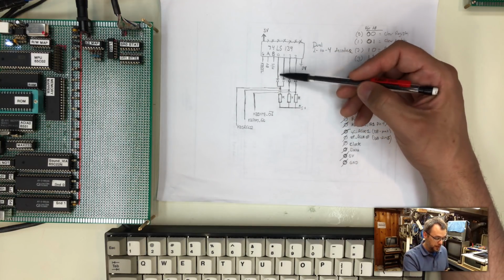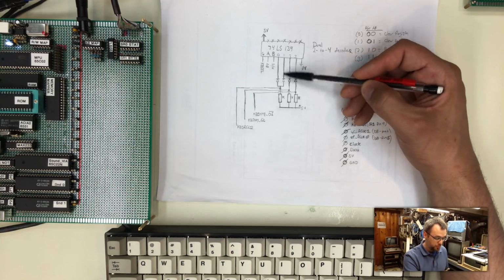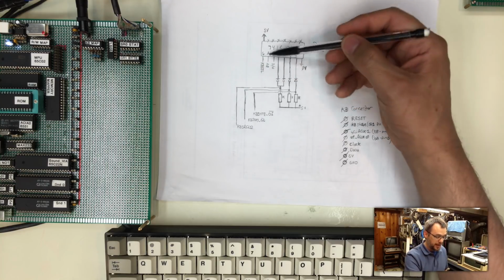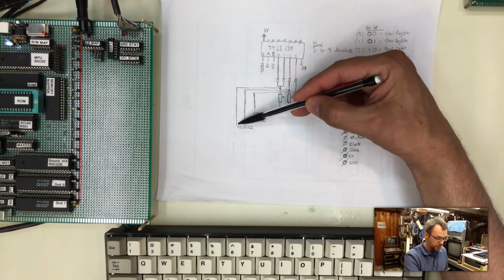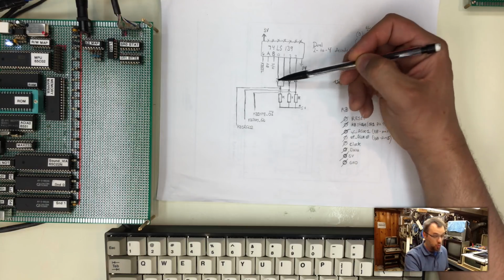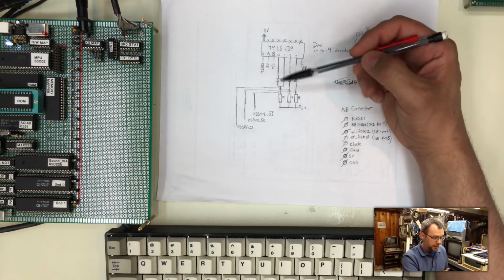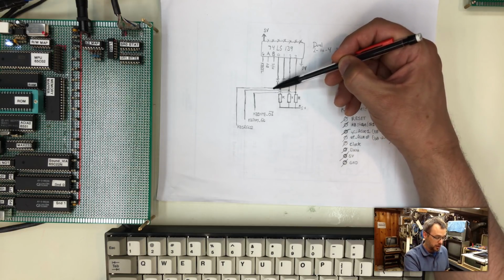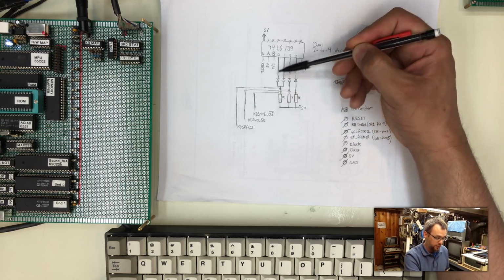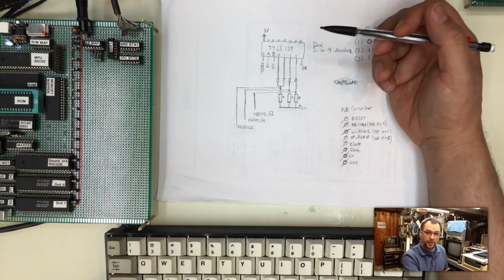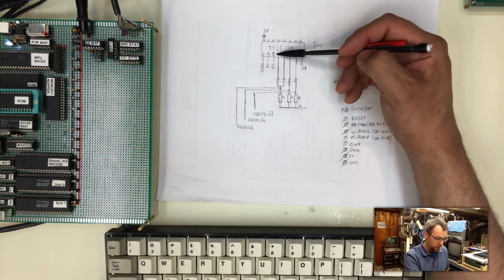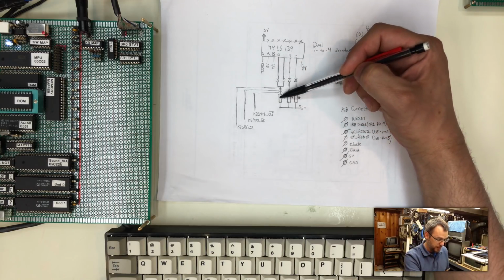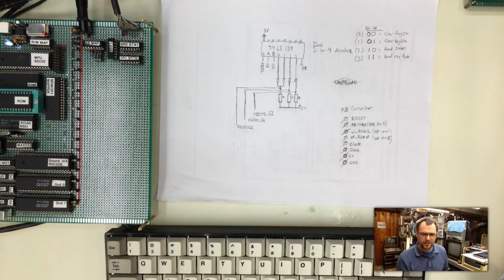But because of the diode here, if this is trying to push any voltage back this direction, it hits the diode, and the voltage will not be supplied over this pin. So it allows either one of these, or both, they would never be both, but either one or both of these to go low, and allow this pin to actually go low by this one supplying the voltage instead of these pins supplying the voltage, if that makes sense.